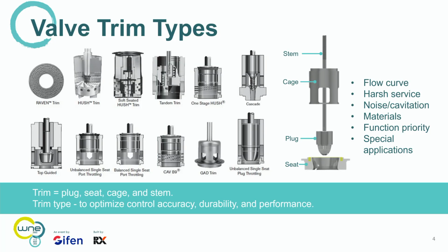And then within the trims, you don't want to have noise, you don't want to have cavitation, you don't want to have flashing. And depending on your condition, the pressure drop, the temperature, you will have to select different types of trims. So as I was saying, you can go from the very basic to the very sophisticated ones, and the very sophisticated ones can be used for almost any application out there in the market.